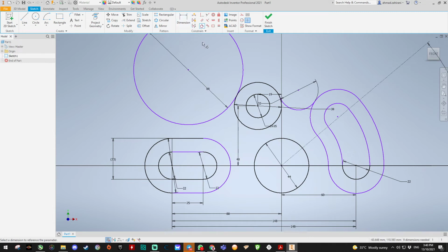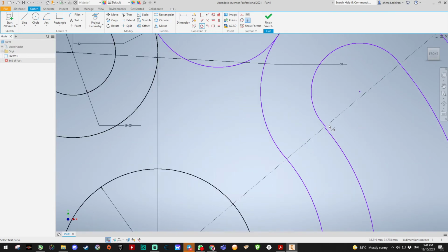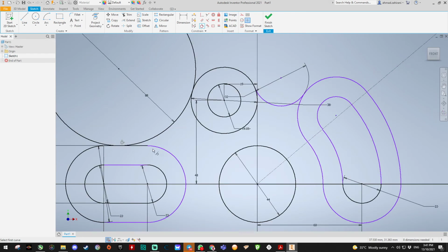So click constraint, this line and this one. Okay, now you can see that the big circle is the one moving rather than the semicircle that we want to stay fixed. So once you complete the drawing of your component, you want them to be, this one is a little bit weird. Okay, later on we address that.